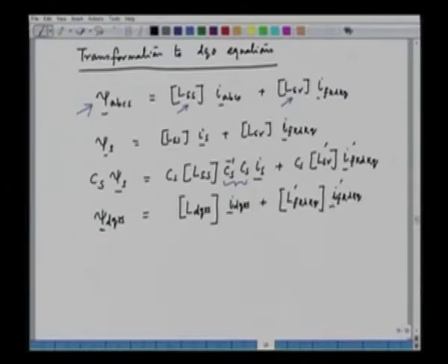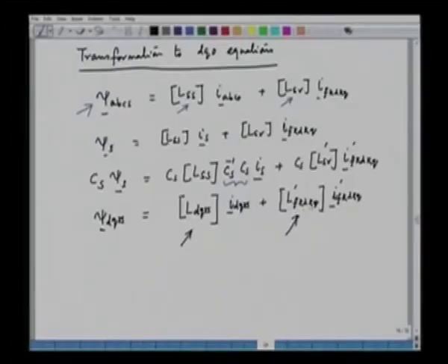So this is what we have here, and we should be interested to know what these matrices are. These matrices are very special matrices. Unlike the previous matrices, that is L_SS, which is a function of theta_r, this L_DQOS and L_FKDKQ are independent of theta. They are basically constant matrices. We will see the expression of these matrices.